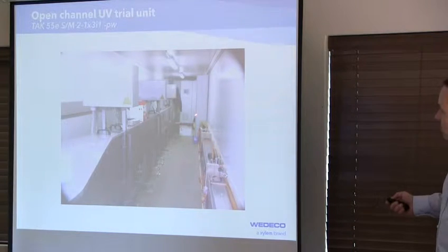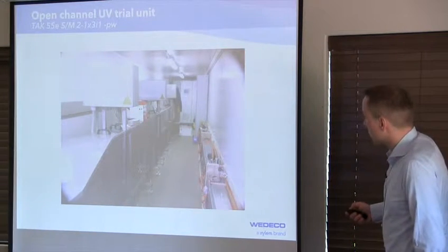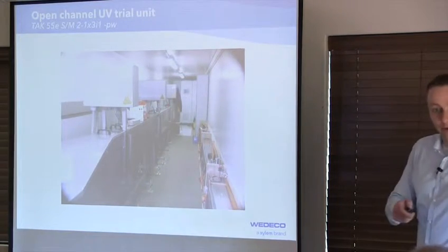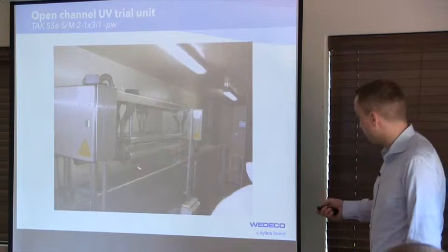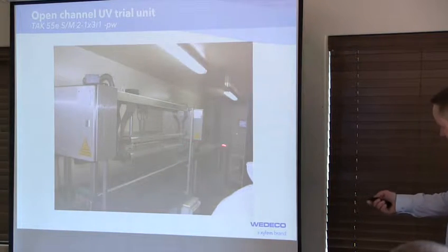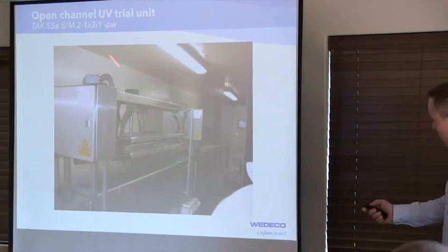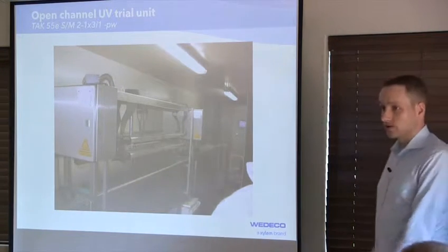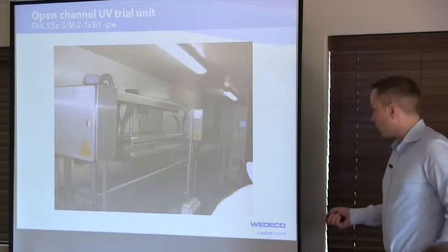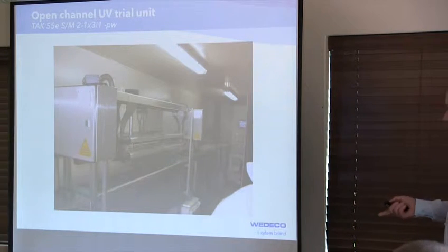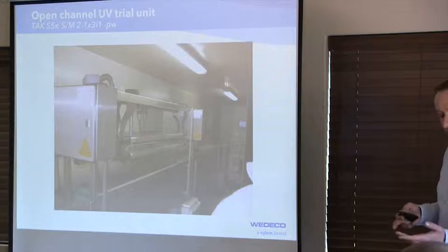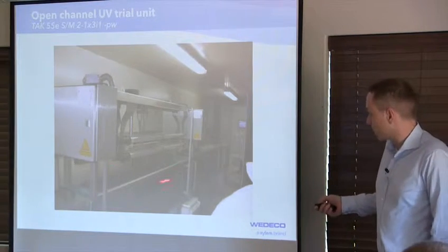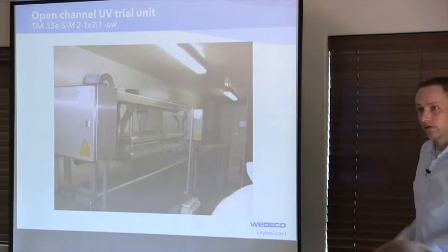Stainless steel channel inside with 3 banks in a row. Each bank has 1 module with 2 lamps deep and 2 next to each other, so it's 4 lamps per module. We have 3 banks, so we can have a multi-bank system, which is better for the actual performance, because you create turbulence after the first bank to get a better mixing.